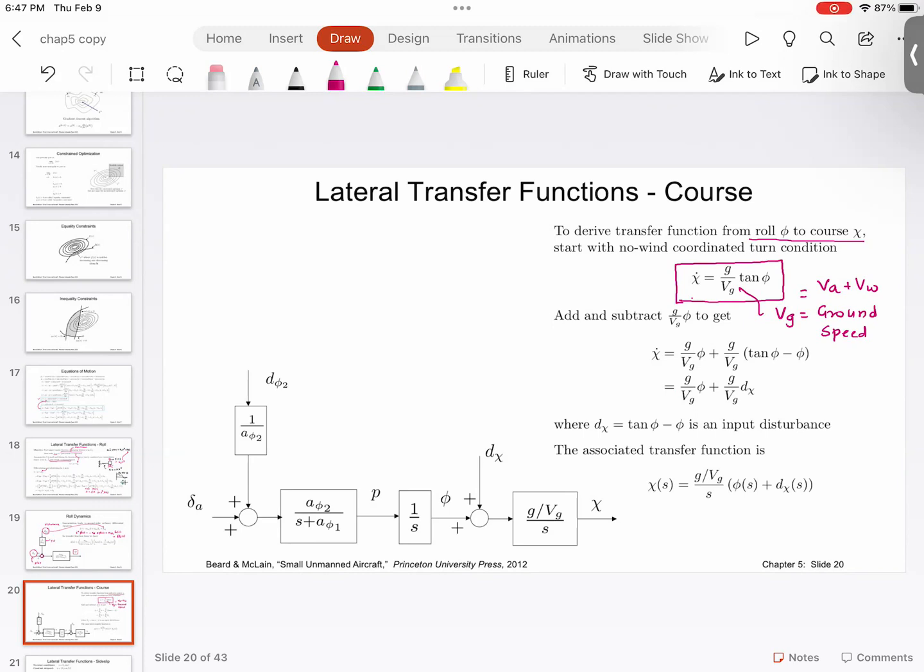Finally, what is our goal? This complicated nonlinear equation should somehow be converted to a linear equation. Somehow we have to find the transfer function and we should be able to implement it in our control system. And then the actuators should move so that the control surface can deflect. Everyone understood this? At the end, what's going to happen? Those hydraulic actuators of the aircraft will deflect the control surface depending upon the aileron input. And then basically the aircraft dynamical equations of motion will be modified and the aircraft will behave the way we want.